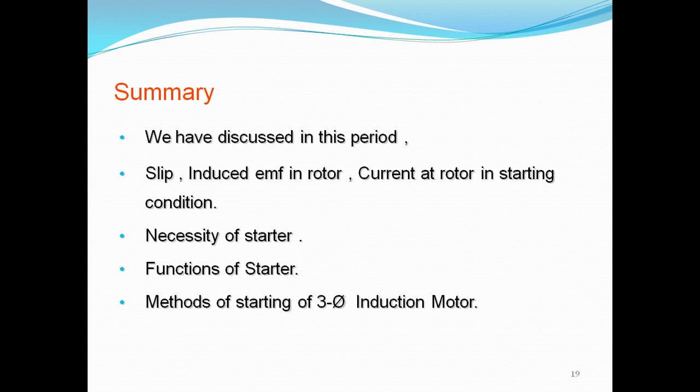The circuit diagram shows the auto transformer starter. This can be made to operate as an automatically controlled starter so that the contacts switch from start to run position when the motor reaches 80% of its rated speed.